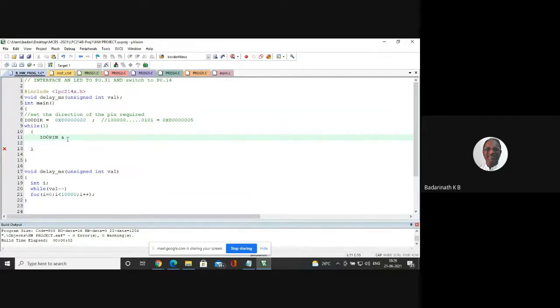You have to prepare a pattern. That means you are making all the bits 0, 0, 0, 0, the 14th bit you are making 1, and the remaining bits 0, 0. So this is one method: you write the pattern, convert it to hex, and use it in the AND operation. There is another method, a shortcut method in C, that we can use, to generate a 32-bit pattern where the required bit is 1. How? You want the 1.